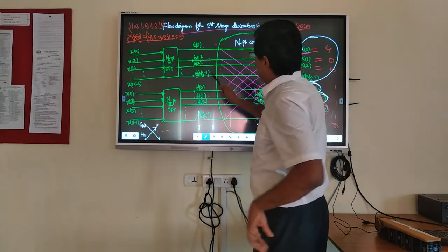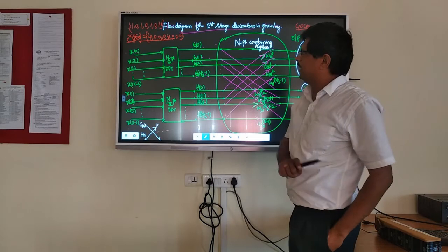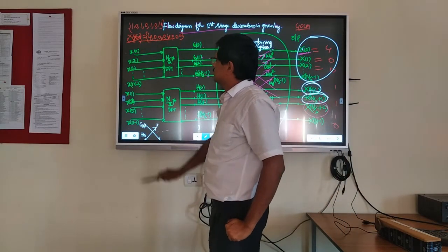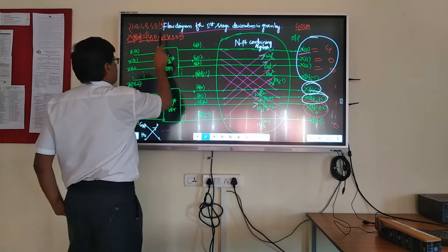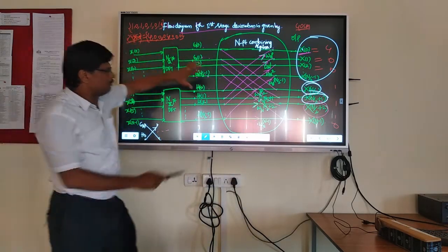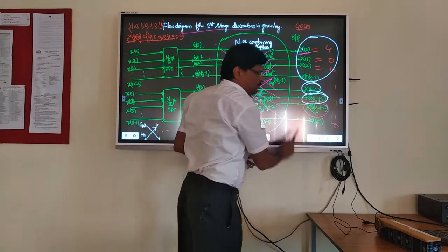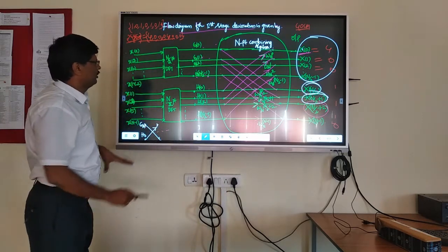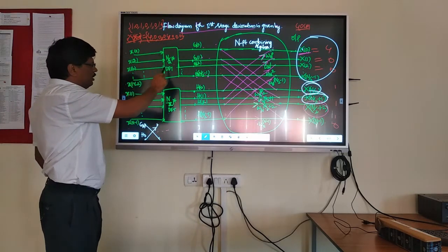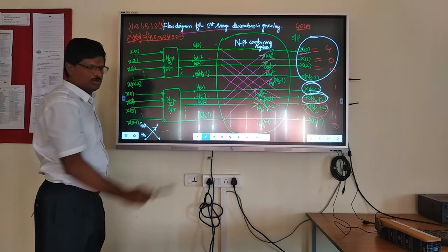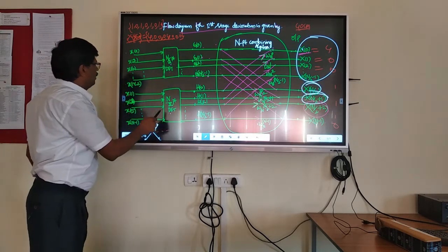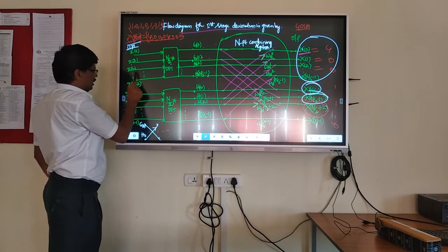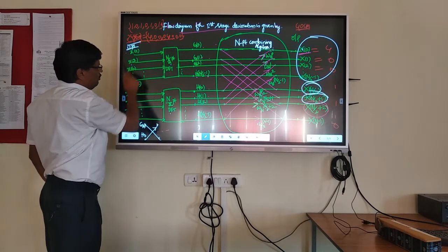This flow diagram for the first stage of decimation is given by, for example, let's say x of n is the sequence 10101010, and X of k is 4 0 0 0 4 0 0 0. These are the frequency samples, the DFT outputs. This is the input, the time domain input. How do I write it now? The N-point is divided into two N/2-point DFTs, one N/2 DFT and the other N/2 DFT. This is G, this is H. The inputs are like this: x0, x2, x4, up to x of N minus 2, the even inputs.